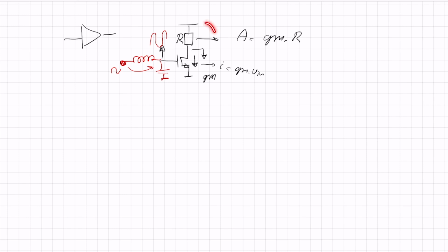And that means that the circuit behind it can have a little bit more noise, because we already have passive amplification. So the amplifiers right at the antenna are typically very simple circuits, in the order of just a few components, as I've drawn over here.